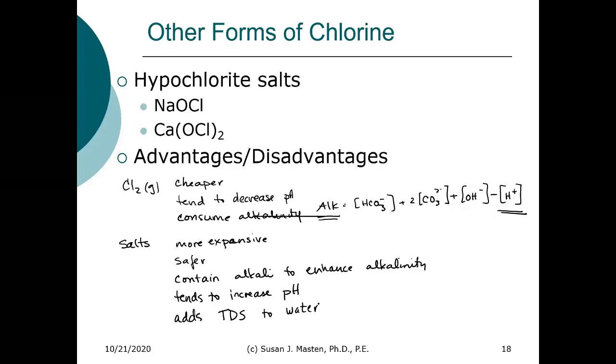Exactly, because originally the plant was on the outskirts of East Lansing, and then as subdivisions built around it, there was a concern for the safety of that population, so they switched from chlorine gas to sodium hypochlorite. On the other hand, the Williamston water treatment plant, which is in a rural area of Williamston, where there isn't a significant population surrounding it, uses chlorine gas.